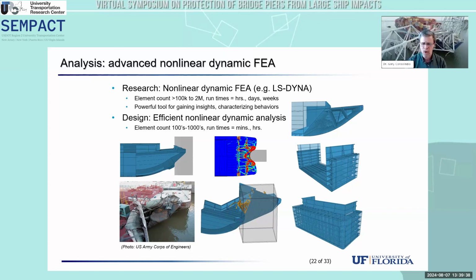Ultimately it comes down to looking at the dynamic characteristics of that structure relative to the time duration of the load that's being applied. So it's not a one size fits all. And that's actually part of the reason that I'm making the argument that a method like the coupled vessel impact analysis procedure makes sense, because you don't have to fit the potential for amplification effects into an empirical model. If dynamic amplification is an issue, it naturally arises out of that calculation. If it's not an issue because the natural period of the structure and the duration of the loads, as you just pointed out, are significantly different, then you won't see significant dynamic amplification come out of that process.